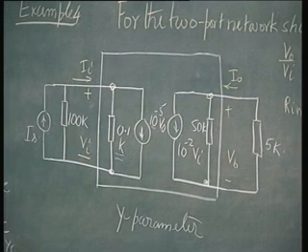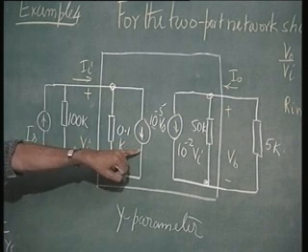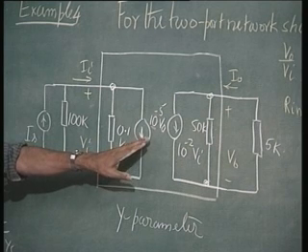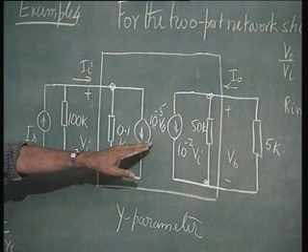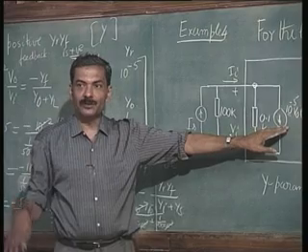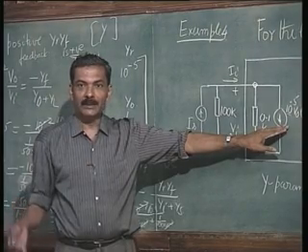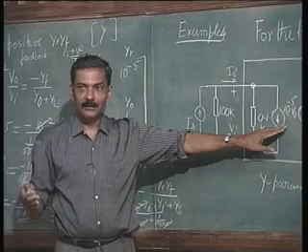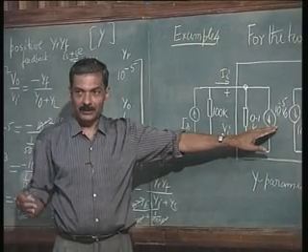So this clearly illustrates what happens because of this dangerous reverse transmission factor, which is causing positive or negative feedback. Now we will later see that we can purposely introduce, okay, positive or negative feedback once we understand the amplifier thoroughly.